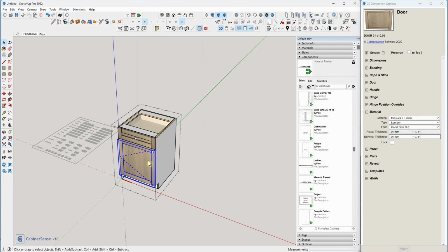I'm just going to get rid of this. I'm going to go back to our palette, and I'm going to change the definition of what I use for the drawer material to be melamine white. Now when I bring out another box, it continues to use the same material. Let's go back and make another change.